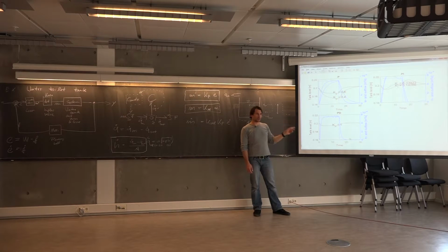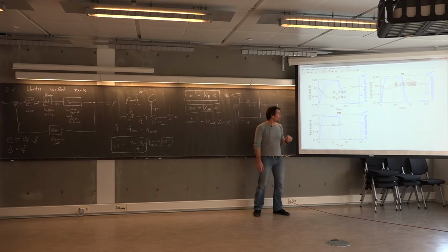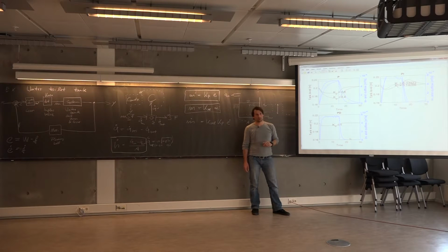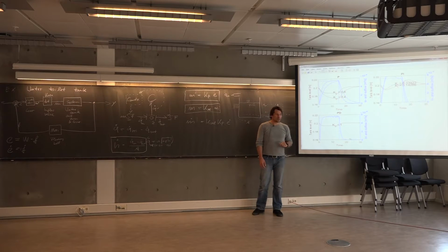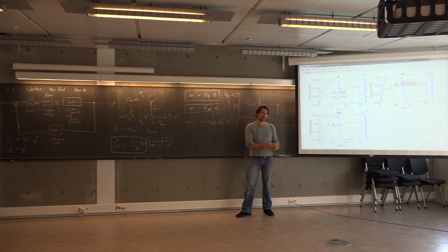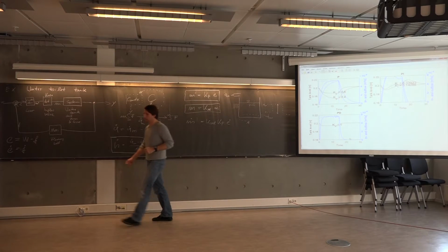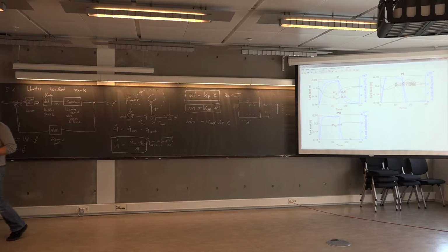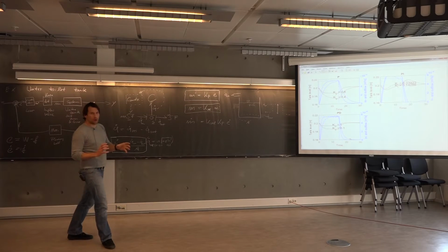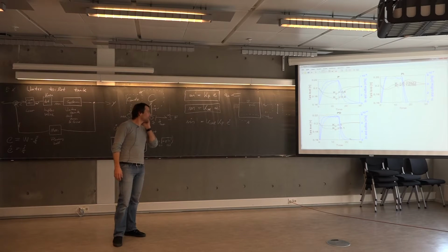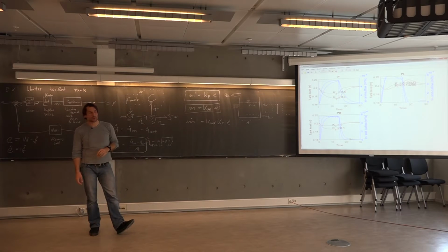Because in order to get rid of the offset, we need to make use of an integral approach. But by using a derivative concept in addition to the proportional control, we speed up the controller's response. Again, we can play around with the numerical values of that KD constant and yield different behaviors here.